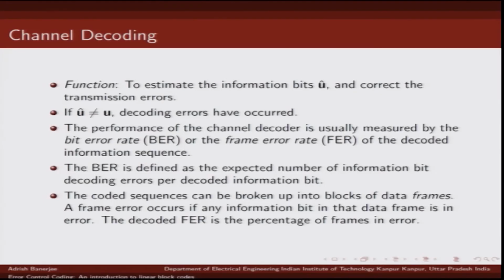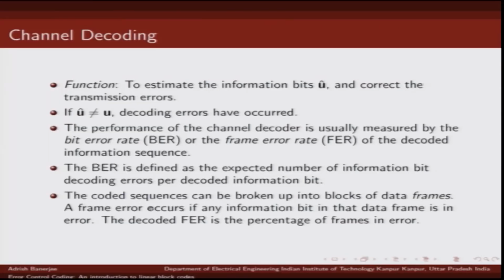Similarly, in packet data communication, if any of the bits in the packet is in error, we say the whole packet, or frame, is in error. So, frame error rate is defined as the number of frames or packets in error divided by the total number of packets transmitted. It is the percentage of frames that are in error.